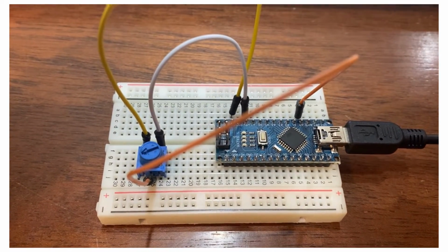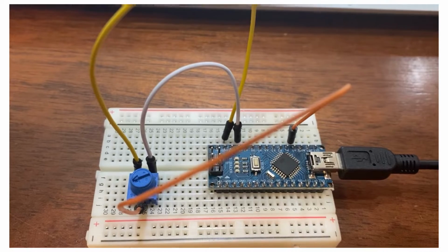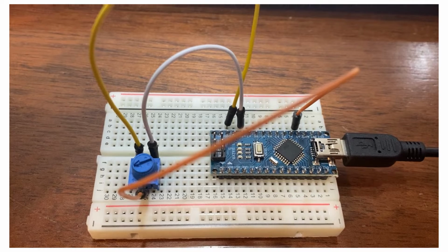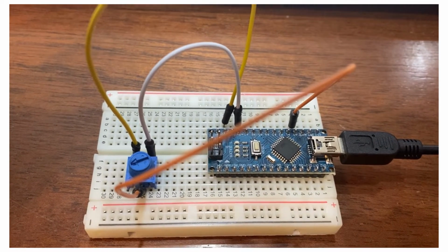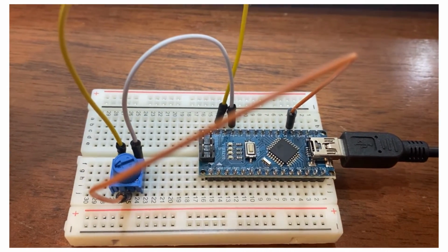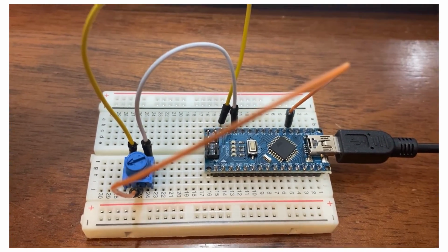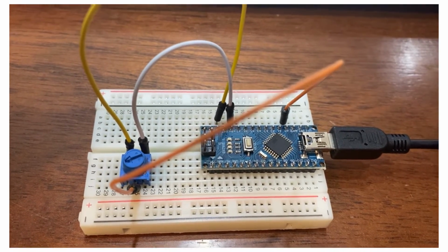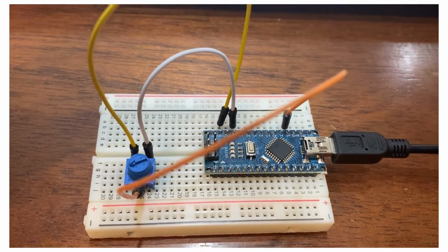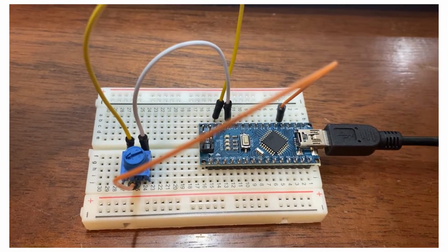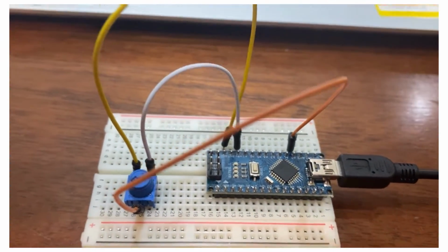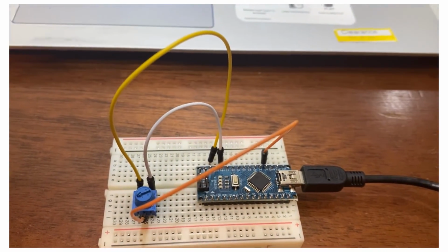Here we have the setup for the Arduino assignment part 2B. It is actually the same circuitry as the Arduino assignment 2A. The only difference is this time we want our results to be displayed in a little bit of a different way. We want to scale the range of the results. Instead of being able to go from 0 to 1023, we want our range to be scaled to 0 to 5, and we will achieve that by using the float function in the Arduino code. And these results can be viewed both numerically and graphically.